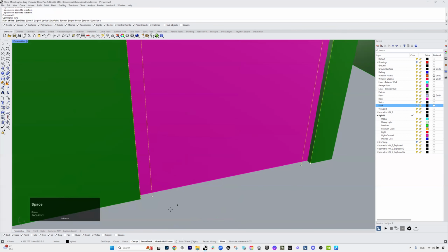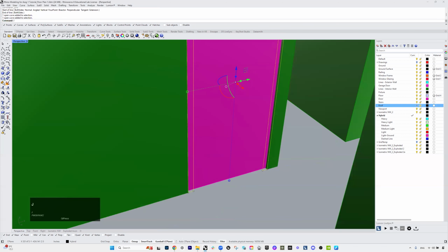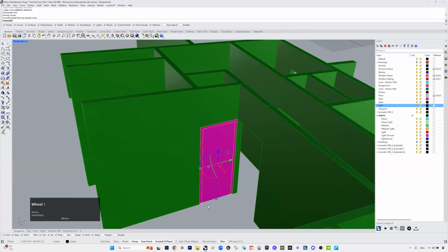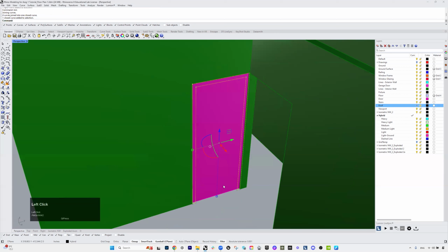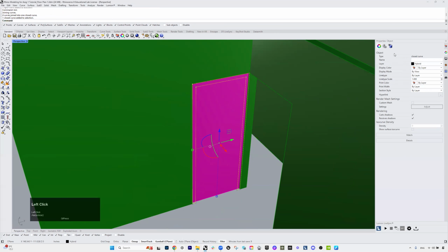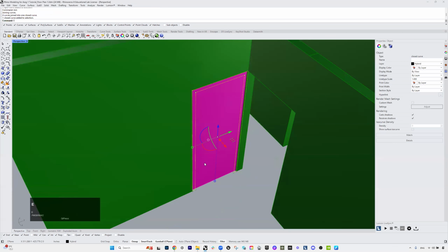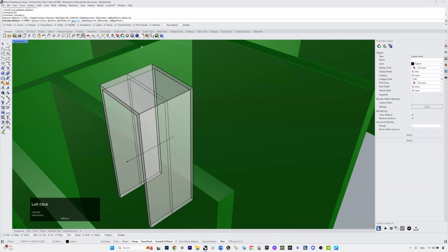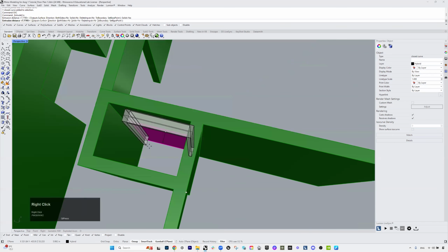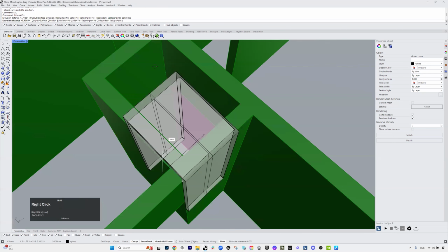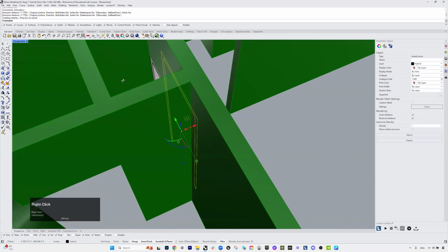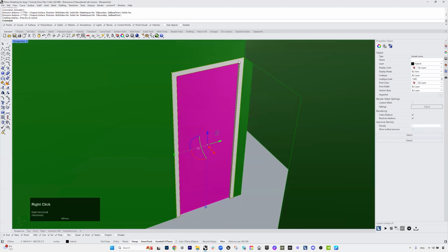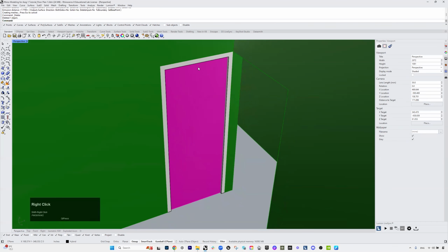Then I'm going to draw a line connecting the interior line and exterior lines, select that, and type join. So now this is one closed curve, which you can see over here. I'm going to extrude this, and I want to make sure this solid is yes. Then extend it out to the depth of the wall, so that could become something like that. And I'm gonna delete the curves.